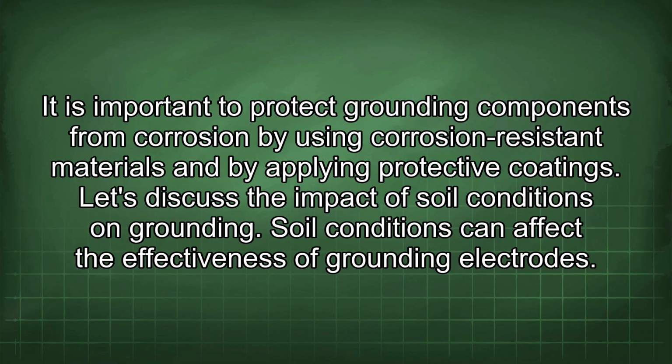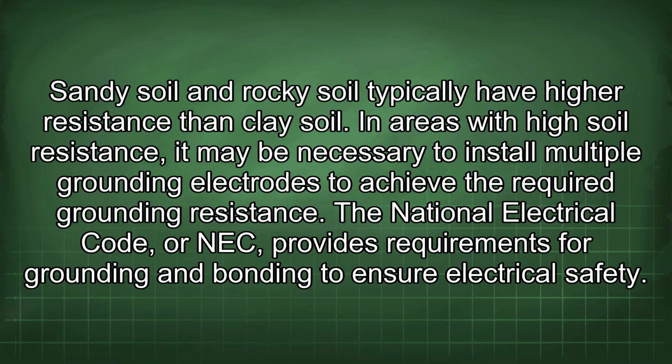Let's discuss the impact of soil conditions on grounding. Soil conditions can affect the effectiveness of grounding electrodes. Sandy soil and rocky soil typically have higher resistance than clay soil. In areas with high soil resistance, it may be necessary to install multiple grounding electrodes to achieve the required grounding resistance. The National Electrical Code, or NEC, provides requirements for grounding and bonding to ensure electrical safety.